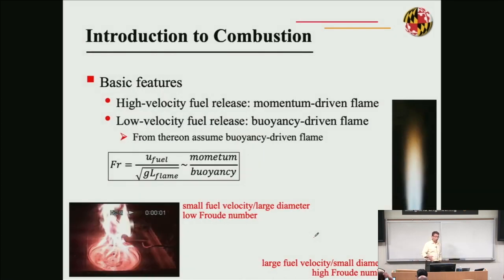So in addition, let's talk now about non-premixed flames from now on. These non-premixed flames can also be differentiated according to the effect of buoyancy, and our flames typically are dominated by buoyancy in fires. To characterize the effect of buoyancy, we typically introduce a Froude number. A Froude number is a characteristic velocity that represents the velocity of the flammable vapors as they are injected into the flame zone, divided by a characteristic velocity for buoyancy. When you study buoyancy, the velocity always scales like the square root of g, the magnitude of the gravity vector, times the length scale, and times maybe a delta T over T.